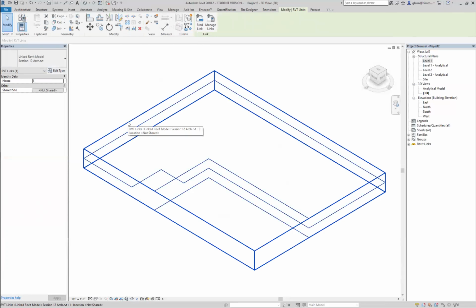That is the look but don't touch box. So you can look, you can query, you can find out what the architect has done, but you can't actually change the architect's work. And vice versa. You'll appreciate that the architect can't move your columns and beams around, since you're responsible for them. So you can always see the other person's work, but you can't actually change the other person's work.